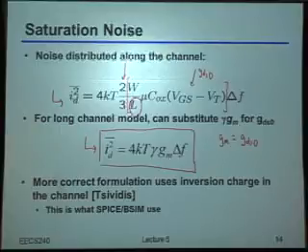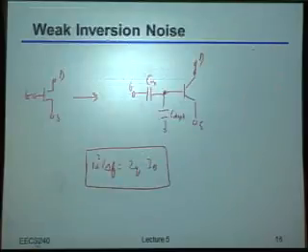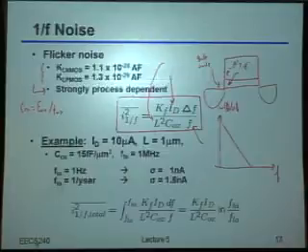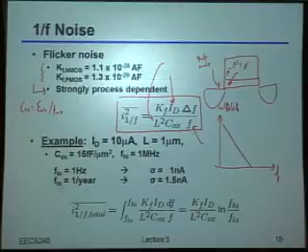Well, if I've now done that, then remember we said that making things larger in space, meaning averaging over more events, makes it better. Exact same thing here, right? Or really just to say it another way, if you increase the channel length, then for the same drain current, your GM gets smaller. So for the same voltage that you changed at the gate by moving that electron on there, once again, you have less drain current effect at the output. Does this make sense to everybody?